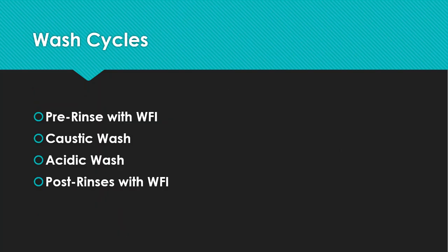Okay. As far as wash cycles go with clean in place systems, there's typically a couple of stages here. A lot of times WFI is going to be used because, keep in mind, these areas that are getting cleaned, these areas that are getting sterilized, are areas that your product is coming in contact with. So water for injection is preferably used here because it's coming in contact with a surface that will be holding the future batches of whatever type of pharma material that you are making. So pre-rinsing a lot of times has to happen. Water for injection is going to be used for the pre-rinsing.